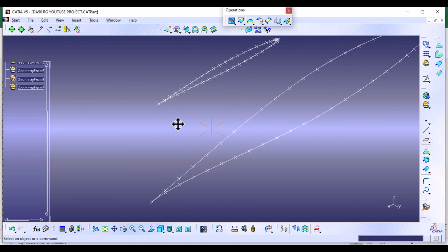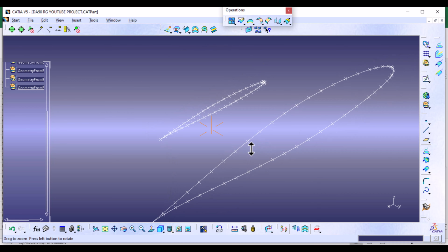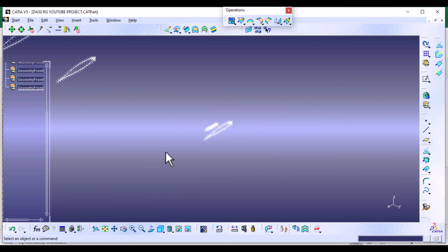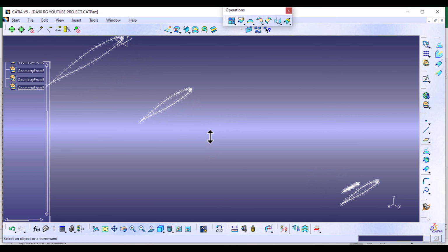And what I was trying to explain earlier, you can see this is the XY plane, but this is ZX. But this top camber right here needs to join with the top camber on that side. And the bottom camber needs to join with this bottom profile. But if we did not plot the mirror image, this would not happen. But we are also going to see that when we are plotting the lofts, the surfaces. So let's go ahead and do that.